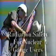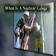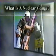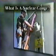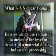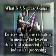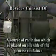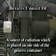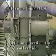with nuclear gauges. But before going into safety, just what is a nuclear gauge? For our purposes, we'll use the term gauge or nuclear gauge to describe devices which use radiation to measure the level or density of a material during industrial processing. These devices normally consist of a source of radiation, radioactive material, which is placed on one side of the process container, and a detector placed on the other side.